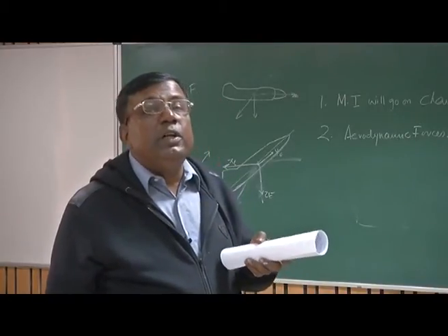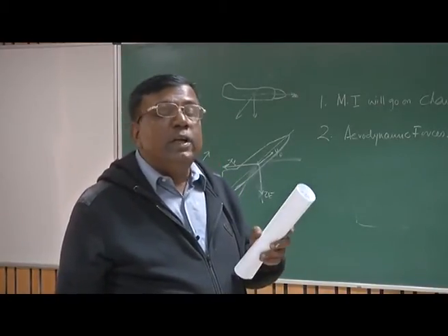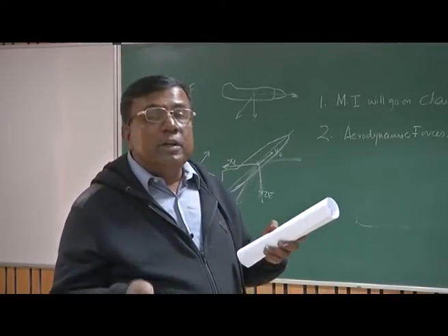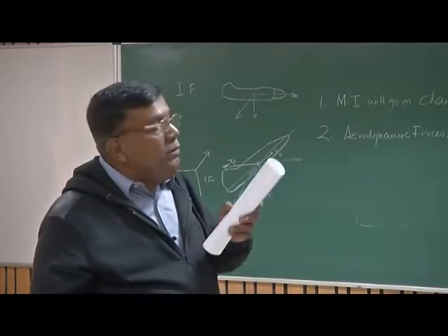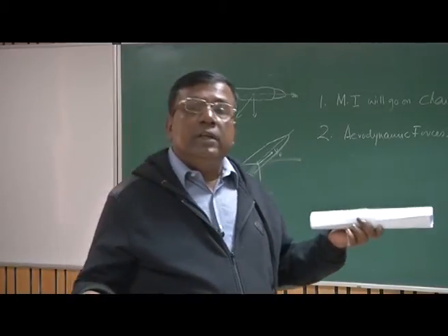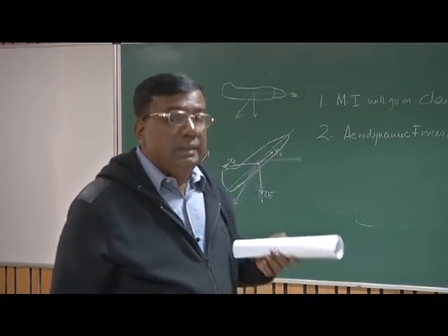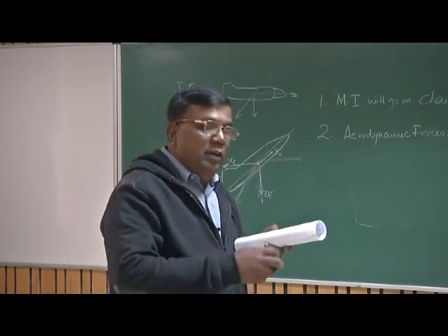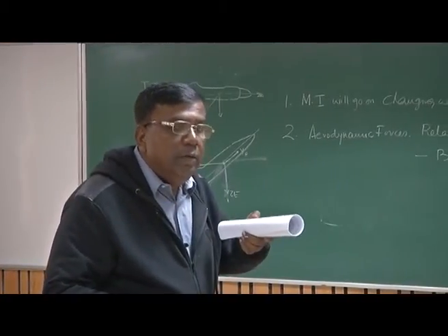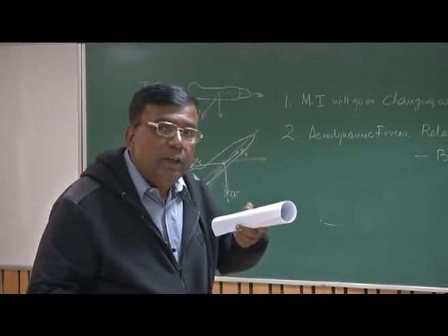If it was with respect to inertial frame, then as the body rotates, the inertial frame is not rotating. So, there will be change in moment of inertia. Now, if I work on body frame, as the body moves, the axis also moves. So, moment of inertia will remain same, no issues. Second thing, if I am working in a body frame, I can get the relative speed of the airplane with respect to the medium.